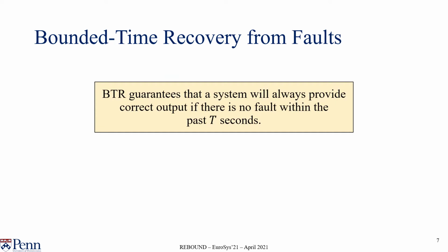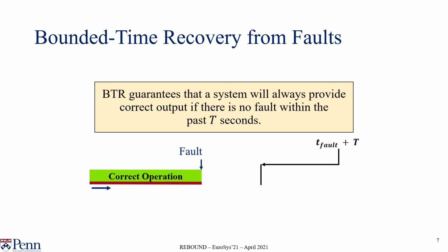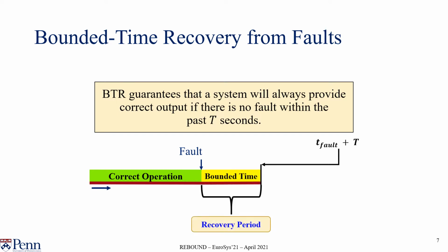So our approach in this work is to provide a guarantee we call bounded time recovery, which basically says that the system will always provide correct output so long as there's no fault within the past t seconds. So if a correctly operating system experiences a fault, we have a deadline of t seconds past the occurrence of the fault by which to have recovered the system. The recovery can occur at any point before the recovery bound has elapsed. After we have recovered the system, we will resume correct operation.